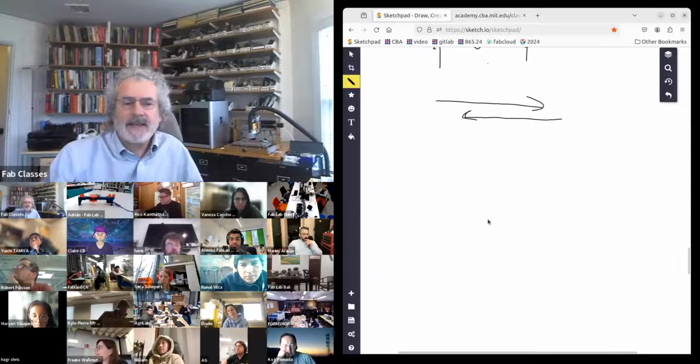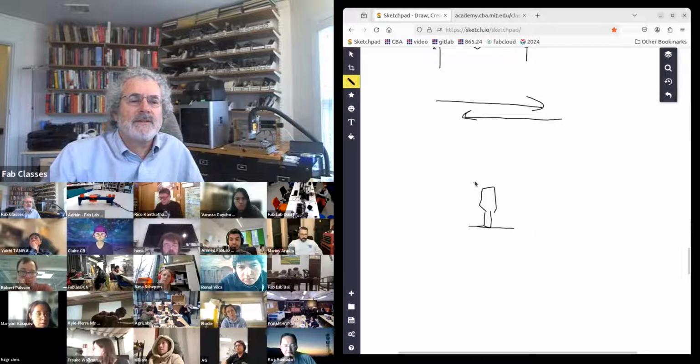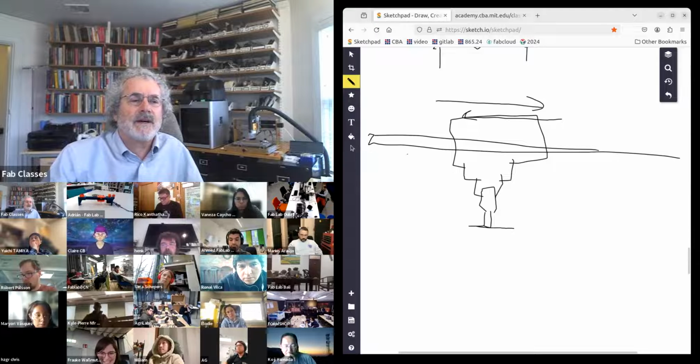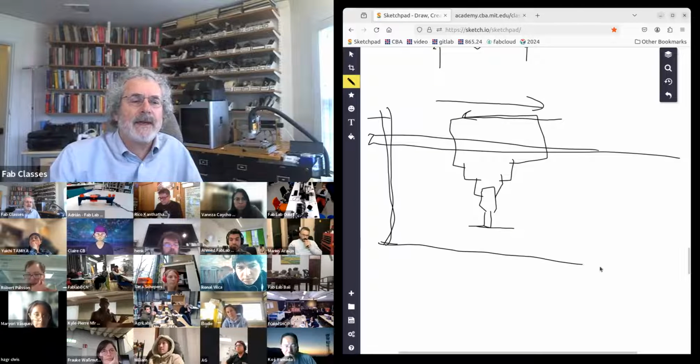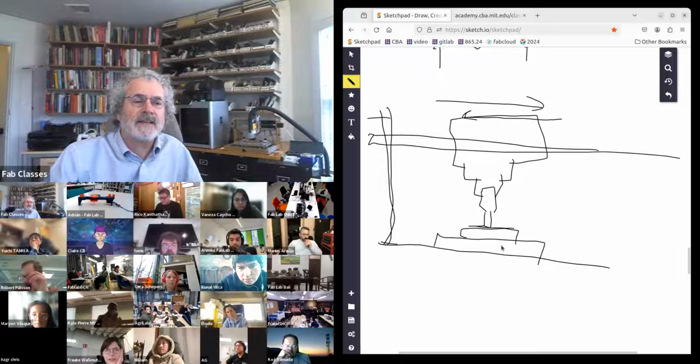Force loops are going to be a key concept. If this is a tool cutting out a part, like one of your circuit boards, it goes into a collet. The collet goes into a spindle. The spindle goes into a z-axis. The z-axis then might go to an xy axis, to this axis. This goes to a bed. The bed then has a platform and then stock, and we eventually get to here.